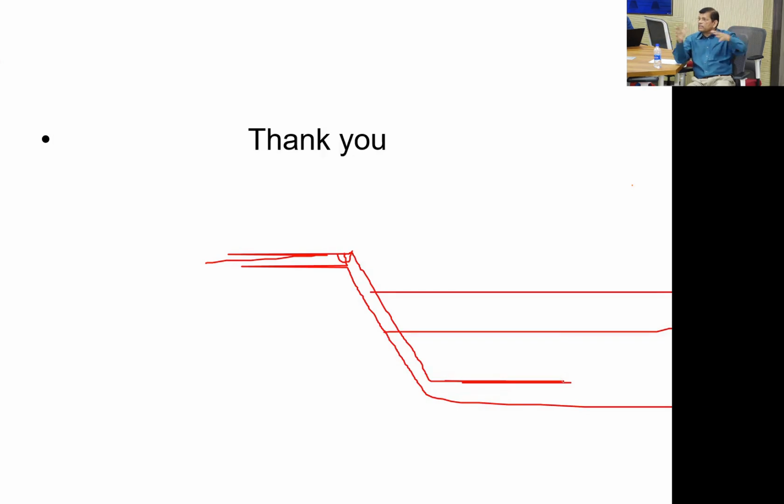If it is open, then it is exposed to the atmosphere, and then the role of the liner will not be that. The liner should not be exposed to the atmosphere. Until it is filled up to the dike, it will be exposed. There will be rainfall and a lot of other things. You have to monitor that liner constantly and make sure that the liner is good. And in our installation, we do a lot of tests also. After we install, we go and do the test.